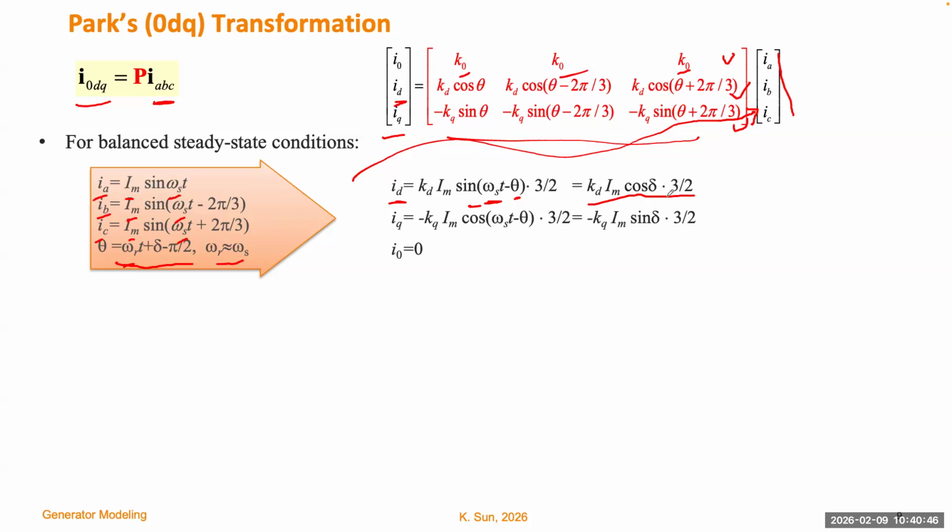If you think about a lot of generators, they revolve together, exactly synchronized. You can define any generator or their center of reference as the reference for delta. Then all the delta will be constant. So this is constant, and there will be a factor of 3.5. That's also constant, and this is completely constant. Also, IQ is constant. Definitely for the balanced condition, I0 has to be 0. There's no current going to the ground.